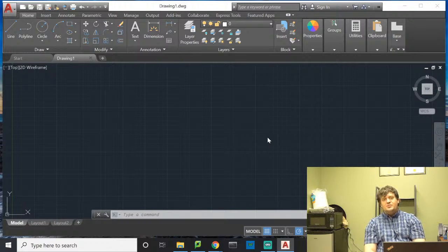SolidWorks is much different in that you have the ability to adjust something like that very easily after something happens, because it's more of a mate-based program based on part correlations and that sort of thing, rather than dimensions-based, which is AutoCAD. Dimensions-based is a lot more challenging to work in. For those of you who have not done any AutoCAD or SolidWorks yet, you will find AutoCAD frustrating and you will find SolidWorks liberating. That almost always happens.